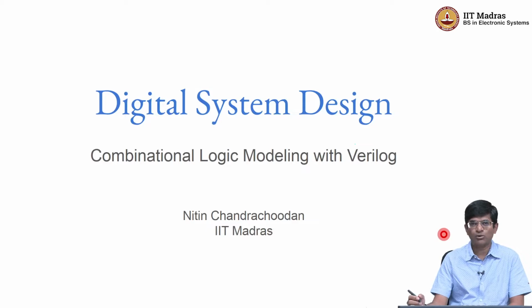For the most part, I'm going to be focusing on aspects that make the design that you are creating synthesizable, and therefore we'll be focusing on a fairly limited set of either language. So when I use the term Verilog, please understand that in most cases it's being used interchangeably with SystemVerilog. The biggest place where that becomes obvious is, for example, the use of the term logic instead of reg or wire in order to declare signals. But apart from that, there may be a few other subtle differences as well in terms of how we use certain kinds of constructs.